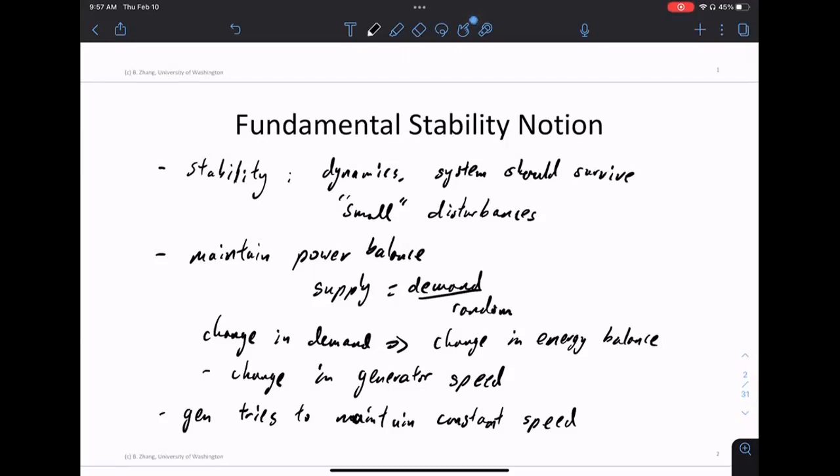But right now, the way it works is we pretend all these devices are in fact like a synchronous generator. So we artificially make your solar panel look like a synchronous generator. Because again, it's electronics, we can do that. But that is not the best use of a solar panel. You're making it look like a synchronous generator, which is not a very good job at doing that. A solar panel can look like many things. It doesn't have to look like a synchronous generator. But what should it look like? What is the optimal way to do this feedback? That is almost completely open at this point.